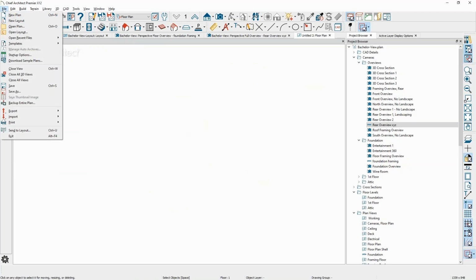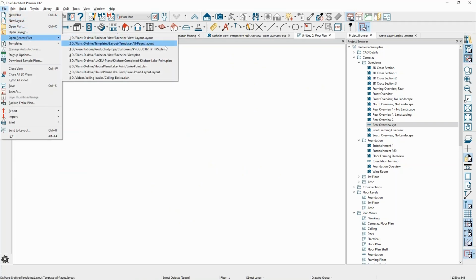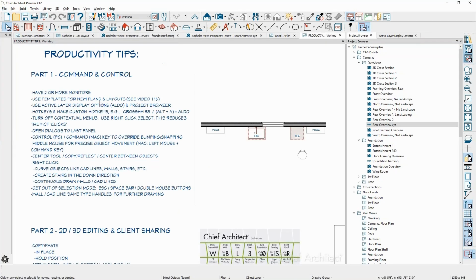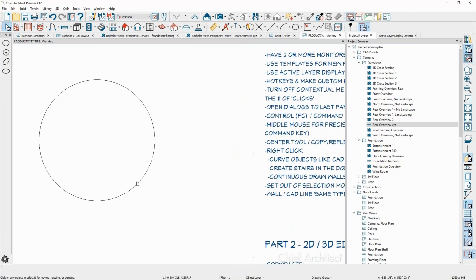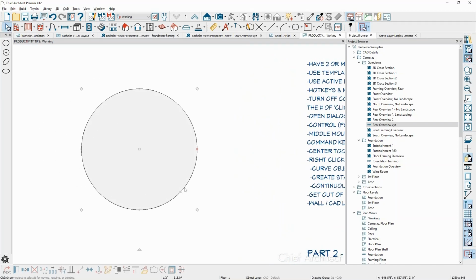To repeat what we did earlier, the question that Paul had asked earlier was, how could I distribute an object, and I think he said a post, around the circle, and he had a specific number, and I think he said 5. What I did was I drew a circle. I took that circle and I used the tool, it's in the lower edit menu, called Convert Polyline. From this point, you can choose that it's a polyline distribution path.